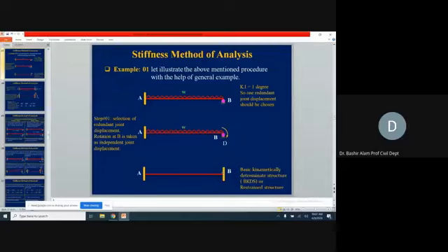Now, when we restrain it here, originally, if you see, moment at this location was equal to 0. But now when we put actual load here, a moment will be generated, and we are violating this equilibrium condition. Instead of 0, we will be getting some moment value here. And we will now have to satisfy this equilibrium condition.